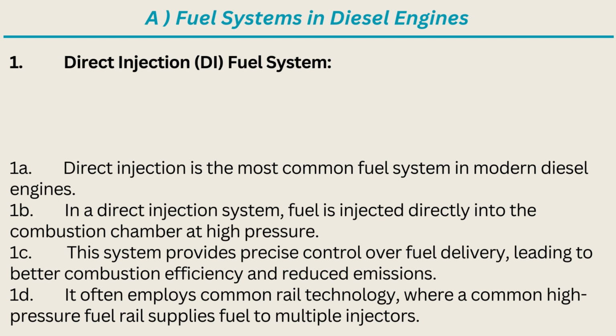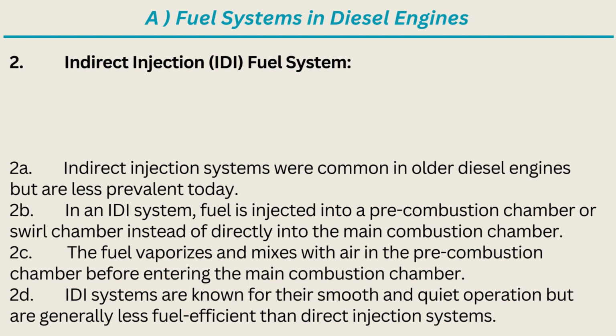1D. It often employs common rail technology, where a common high-pressure fuel rail supplies fuel to multiple injectors. 2. Indirect injection, IDI, fuel system. 2A. Indirect injection systems were common in older diesel engines but are less prevalent today. 2B. In an IDI system, fuel is injected into a pre-combustion chamber or swirl chamber instead of directly into the